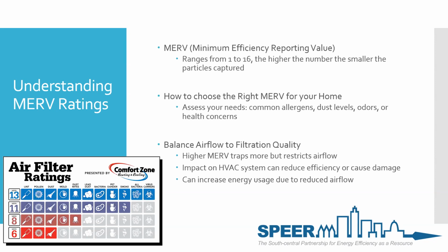So lastly, of course, I just kind of mentioned that a little bit, but buying higher MERV filters may work in your system, but it may reduce the airflow, causing equipment damage or higher than normal energy consumption just for that fan unit to turn. And on that lower left, you can see kind of a snippet I got off the internet.